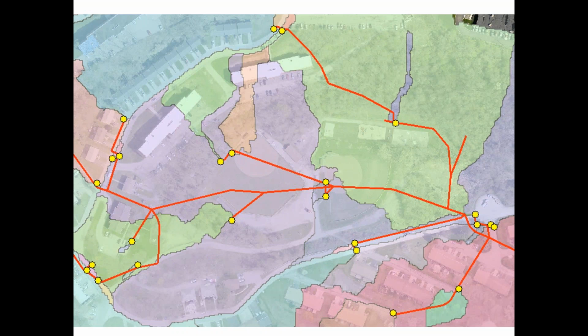That allowed the engineering team to go out and prioritize which catch basins to look at, either because they had little or no contributing area, or because they had this massive contributing area. It also allows them to run different scenarios about what happens if any of the upstream catch basins are either undersized or clogged, and that flow just gets pushed downstream to the next catch basin. For example, you may want to design catch basin capacity to not only handle its own catchment area, but that of 1 or 2 catch basins upstream.